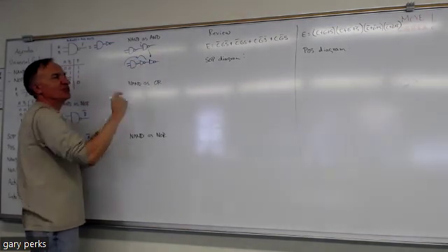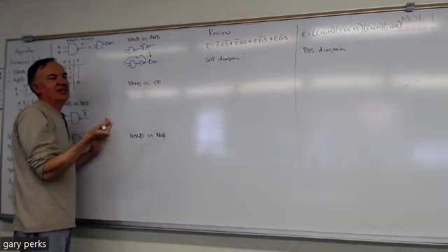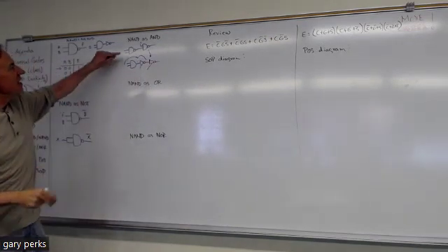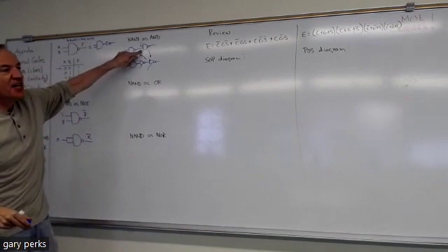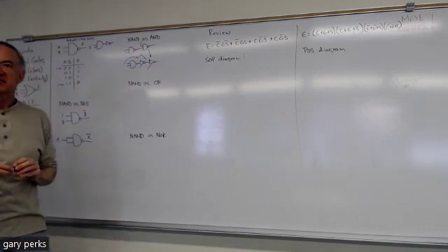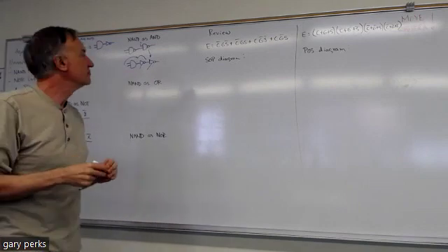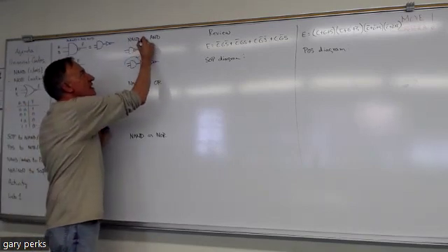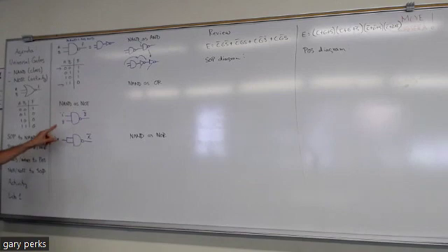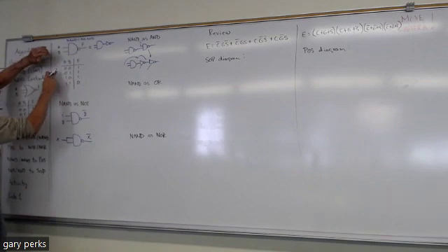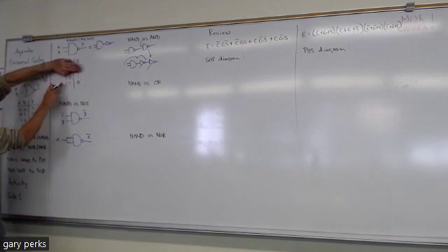Well, what happens if you put two inverters in a row? Yeah, they cancel out, right? So this would just cancel out and it's equal to an AND. So you see, if I take a NAND gate and I put another NAND gate that's acting like an inverter, well, this all together is going to give me an AND gate. The one is what we did here, just that one way to make a NAND into an inverter is to connect one input to a one. Because like we said, if you look at the truth table, the bottom two rows, if I make one input to an AND gate a one, the output's going to be opposite the other input.